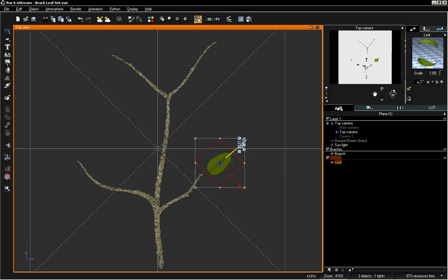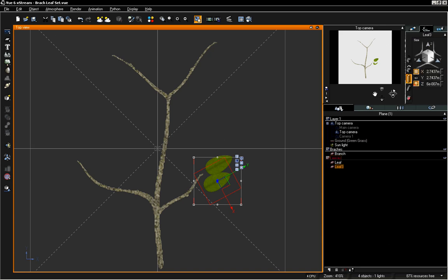And I'm just going to bring this leaf off to the side, angle it a little, and copy and paste, move that over. And now we need to make sure that we're modifying it on the z-axis. So the easiest way to do that is just to go up to our numerics, and then with the move and position option selected, we could just take the z and move it up or down just a tiny little bit. We don't have to go very far with it.